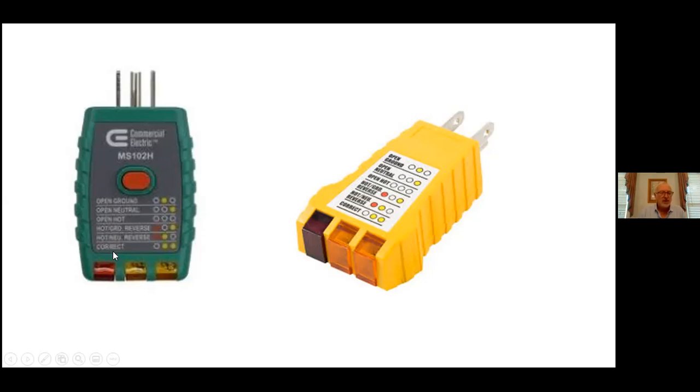And again, you see the same type of thing. We see the correct on the bottom with 2 yellows, etc. But this red button is what we use, especially in kitchens and bathrooms that have been remodeled. This little red button would tell us if that ground fault circuit interrupter, that GFCI, that's supposed to trip when it's near water, is working. The GFCIs are located at the kitchen sink, at the bathroom sinks, wherever they're near water, or on the exterior of the home.